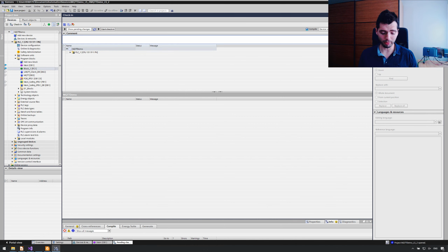and you can put some comments. So maybe updated code in main for added diagnostics, added new block for motion control. Something that makes sense. And then you have this flag, compile. The compile flag is quite important. When you say compile, it means that when it sends the changes to the server, it's going to try to compile the project there with your changes.